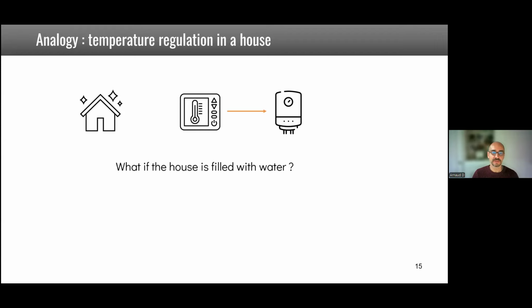Okay, and then you can come to another question, which of course is unrealistic, but just to explain: what happens if the house is filled with water now? So is this regulation law that we said to heat the house still good? Probably not. You know that, of course, water takes much more time to heat than air does. Okay, so if you use this regulation law, you are never going to get to the right water temperature. So that's what I want to stress, that there might be a lot of delay between the command that you give and the fact that it's hot or warm and comfortable in the house.